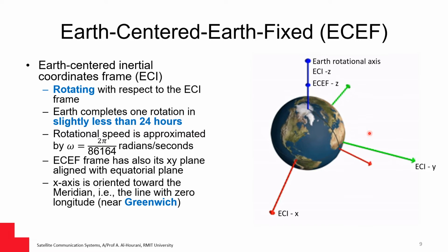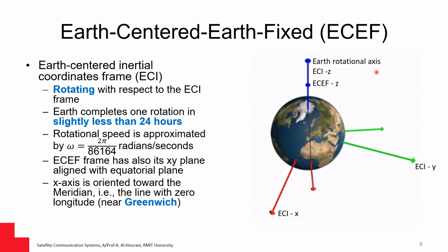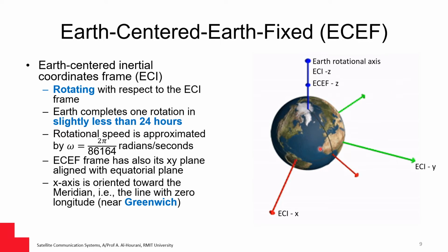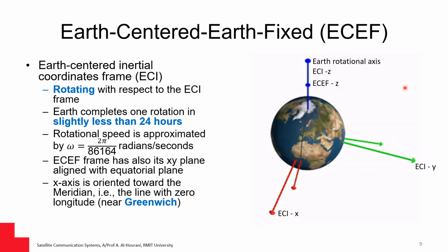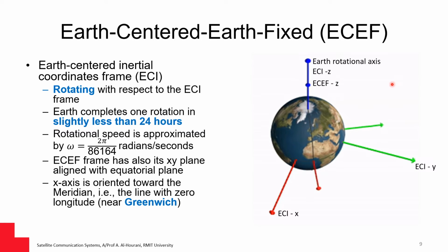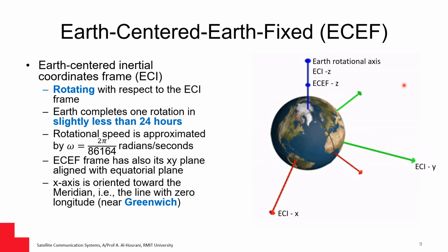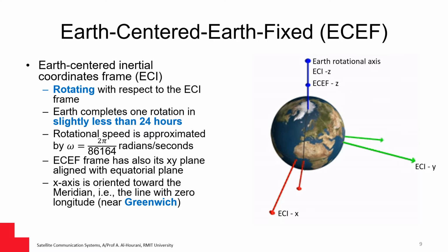Now we will see in the lab how to do the conversions between the ECEF and the ECI. It's worth noting here, if you have a point or a satellite that is described in the ECI frame and you want to convert the coordinates from ECI to ECEF, you need to know the time at which you want to do the conversion, because at different time points you will get different results.